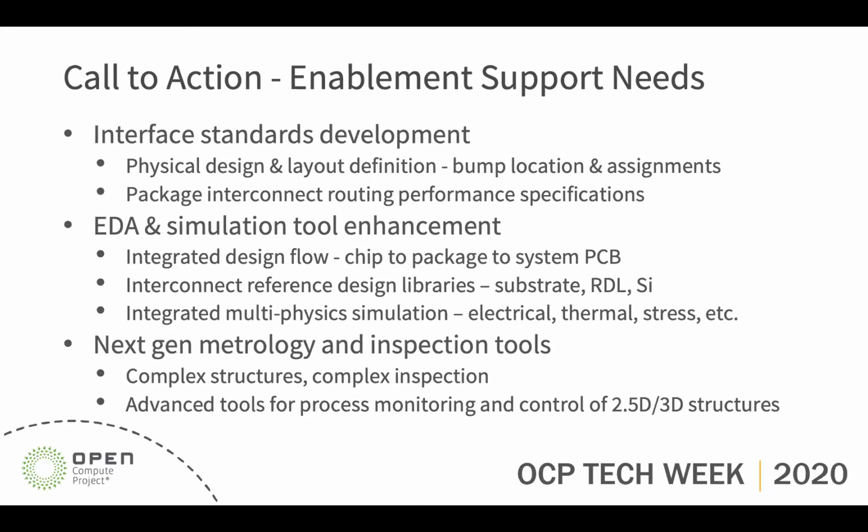The ODSA's effort in the development of these interfaces needs to be extended and optimized for various types of package level integration technologies, including substrates, high density RDL, and silicon interposers.